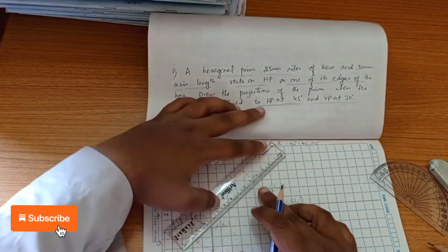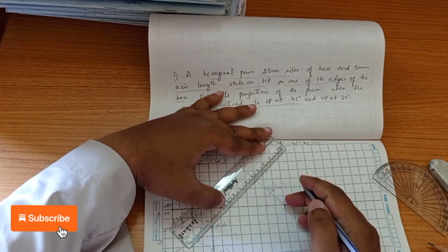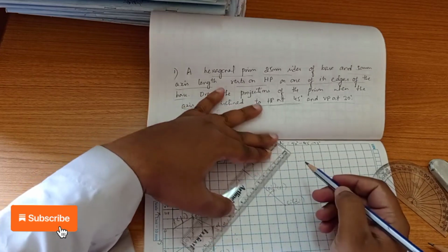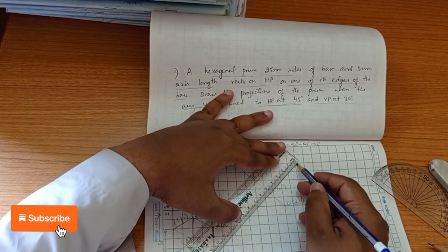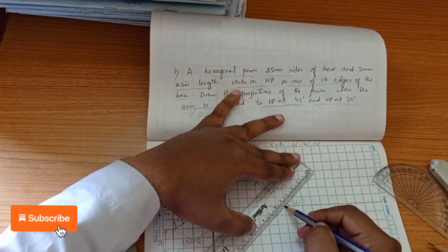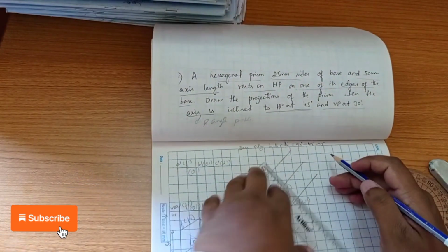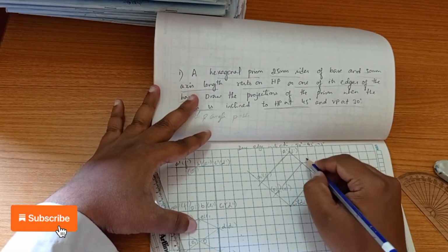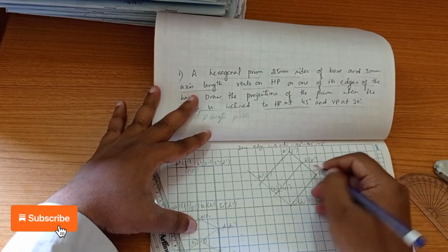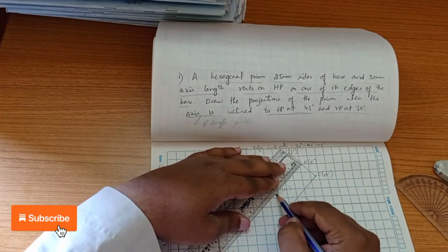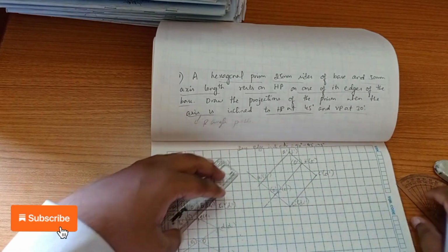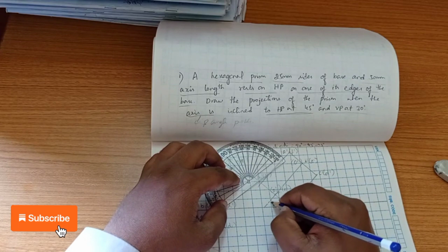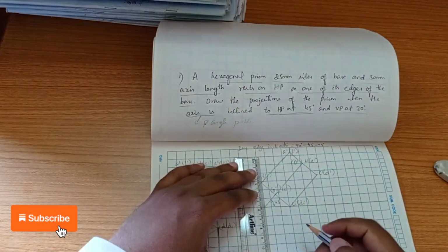Now drawing a line of length 50 mm. So now we can join this. Okay, so I can write A dash, this is B dash and E dash, this is C dash and D dash and this is O dash. So by extending this, here we can show an axis. So if you measure the exact angle you will get it here, it is exactly 45 degrees. So now by projecting downward,